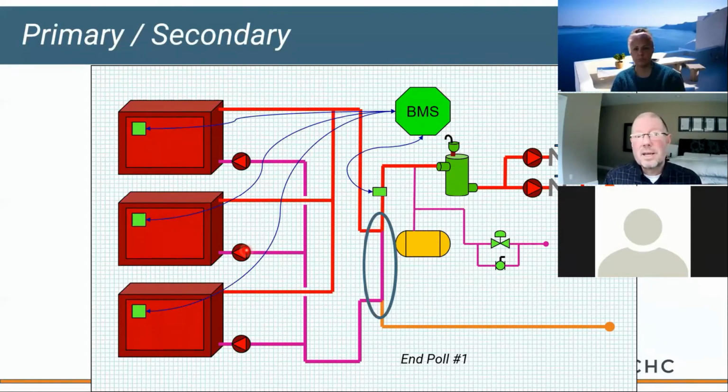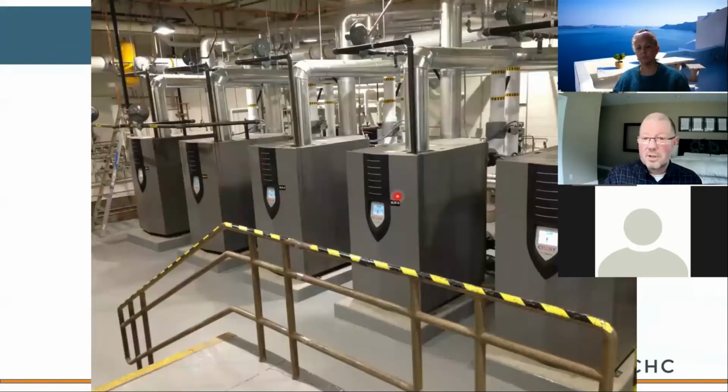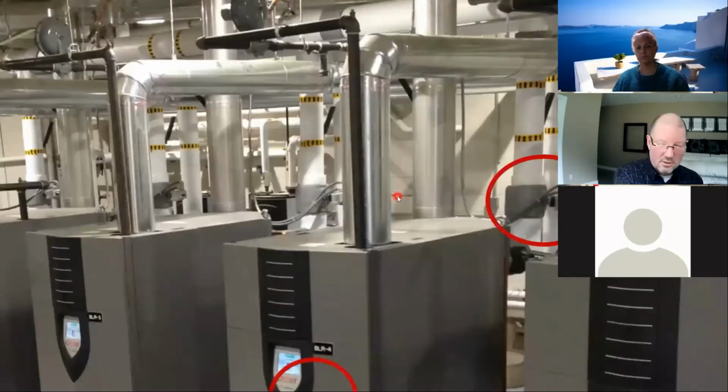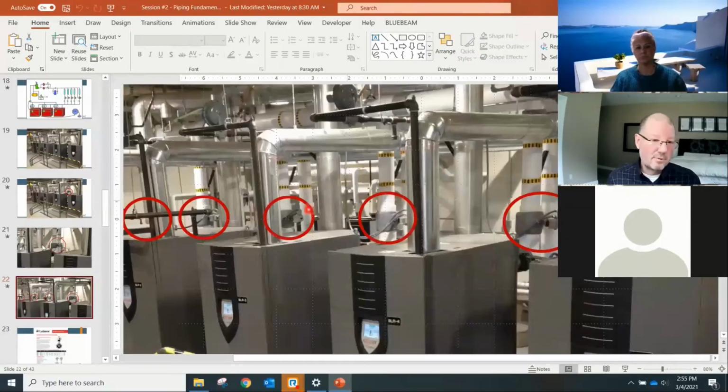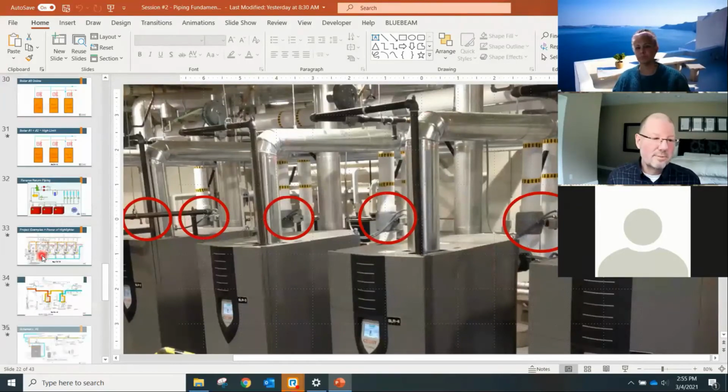The chiller is probably going to have the same setup. So you could control this pump speed to basically maintain a constant delta T as your chiller ramps up or down in production. And meanwhile, you're still doing what you need to out here in the system. I'm not sure I've answered your question. Happy to take it offline if you want to send an email or schematic, maybe some conditions. Happy to help. But yeah, really good question.